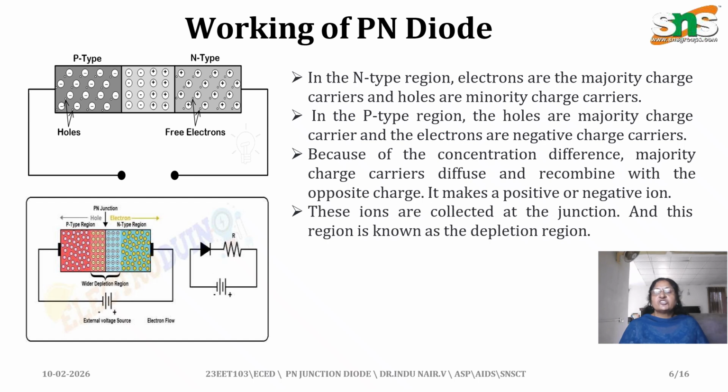It is called the depletion region because the entire region is depleted of charges. When no bias is applied, a wider depletion region is formed, which does not allow further movement of electrons from N-type to cross over to the P-type to form a current.